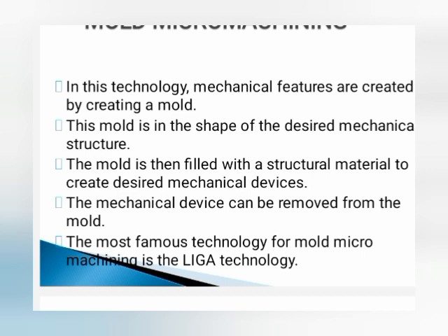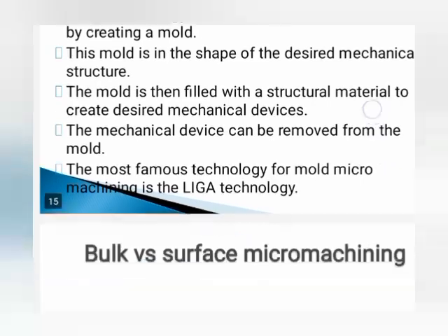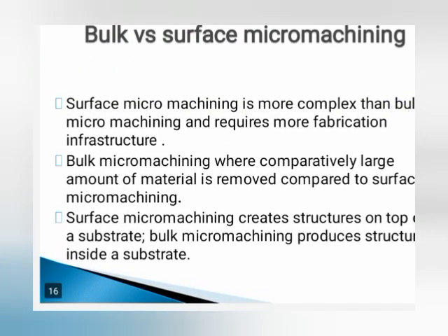So mold micro machining, first of all, creating the mold. The mold is the desired mechanical structure. The mold is filled with the material and mechanical devices can be removed from the mold. The most famous technology is LIGA.